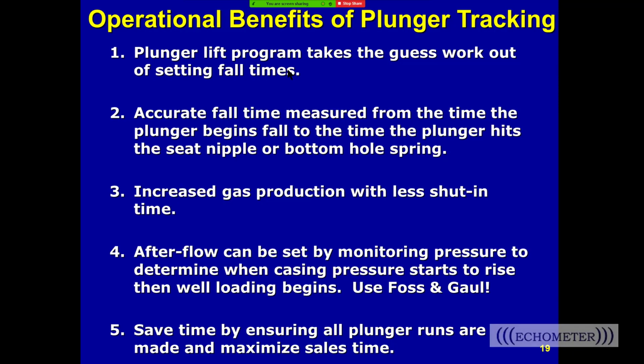You can typically see the plunger fall to the liquid and then rest on the bumper spring. Probably 60% of the time you can see it hit the bottom and see it bounce on the pressure transfer to the bumper spring. You'll maximize your gas production from your well if you have the minimum shut-in time required to get the plunger to the bottom.